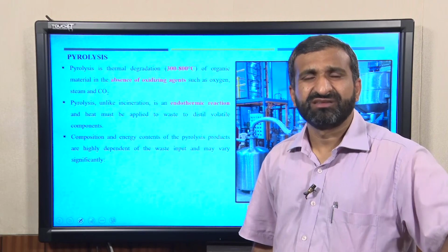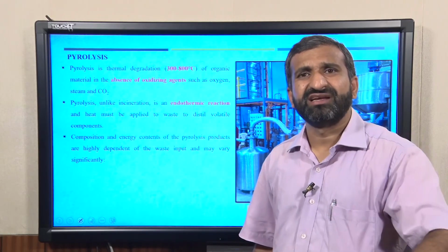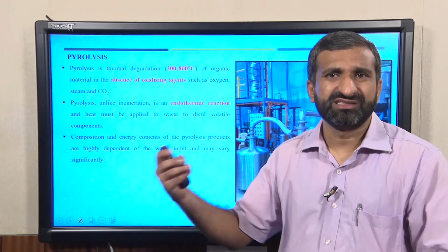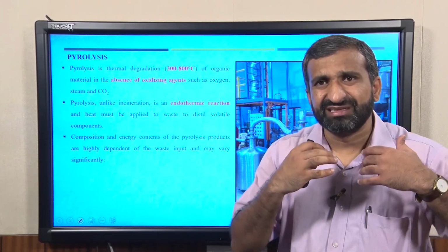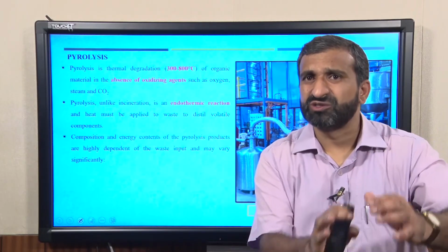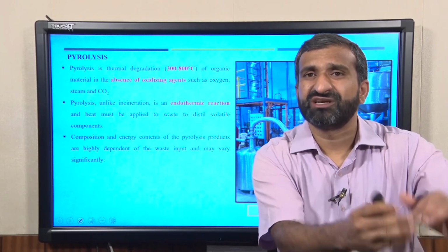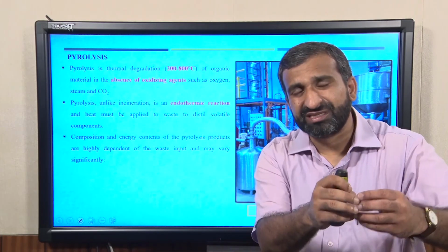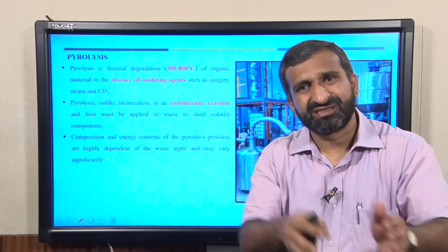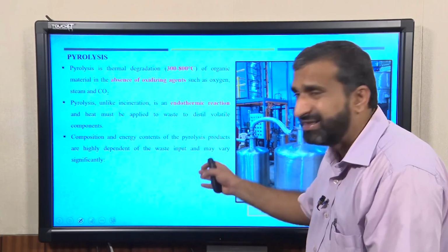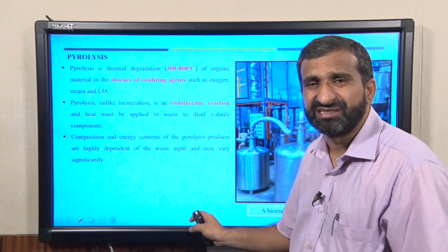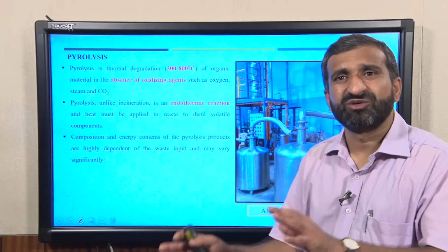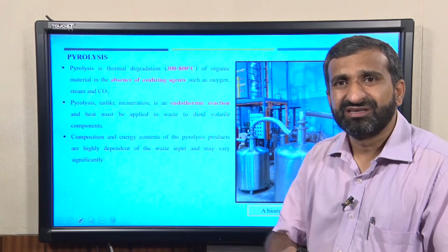For the incineration process, I was also talking about needing segregated material. Obviously, whatever is combustible we can put into the incineration process. But even with 5%, 10%, even 30% moisture in the combustible matter, if you feed it to the incineration plant, there will not be any issue. We can increase the grate length, dry first, and then get combustion. But for pyrolysis, and even for gasification, the composition of waste is very, very important, and the operation will also change based on the daily feed.